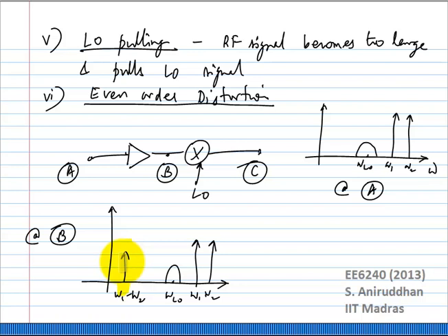It is not a small problem at all, because if the signal you're receiving has an amplitude of, let's take a cellular signal, you're trying to receive a signal which may be smaller than a microvolt, right? Maybe the LNA gain is 20 dB. Let's say the voltage gain is 20 dB, so it's a gain of 10.